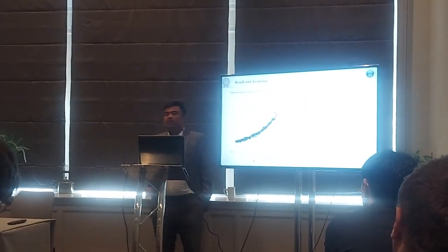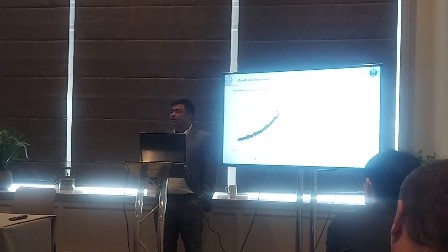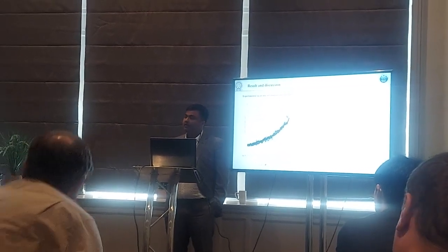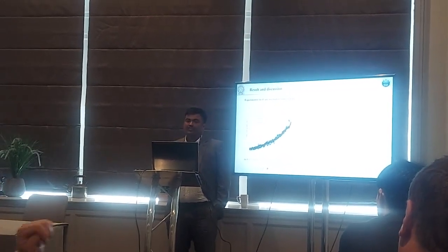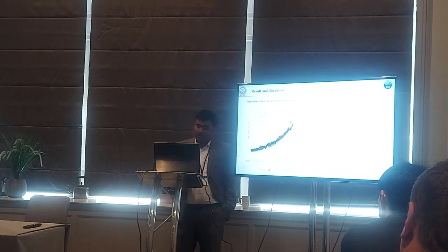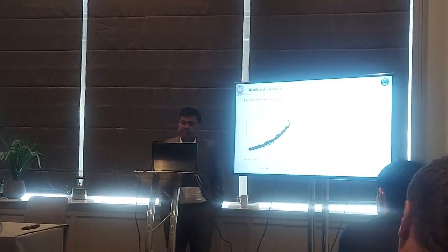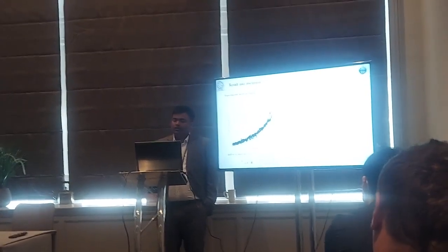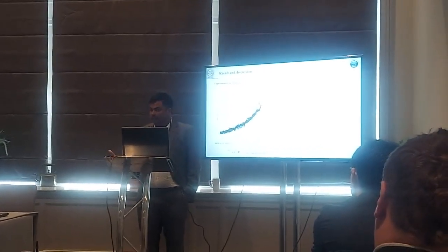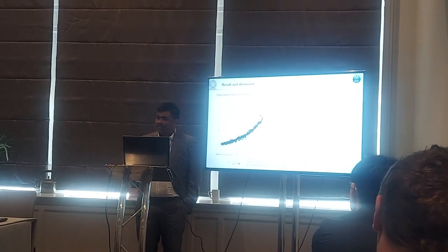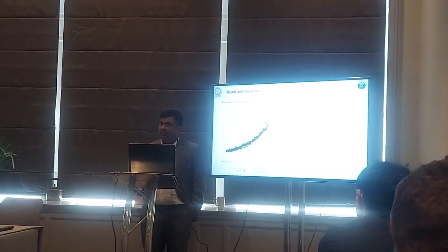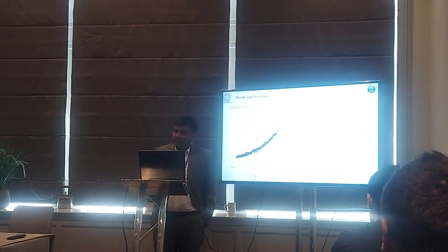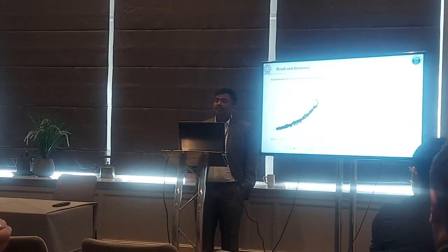The load line displacement rate is the combination of elastic load line displacement rate, plastic load line displacement rate, plus creep load line displacement rate. The ASTM E1457 standard says you take the total load line displacement rate, because extensive creep domination is there. So we use the total load line displacement rate.